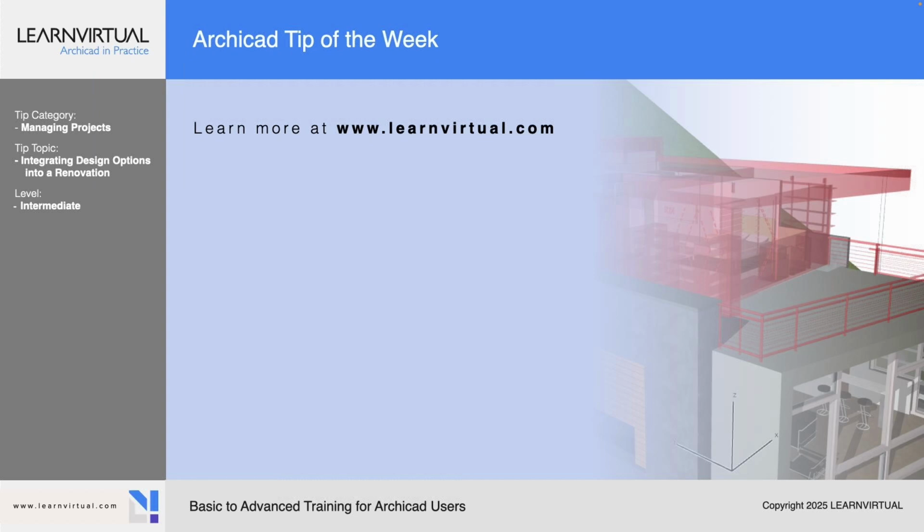The other way you can do it is by relinking it using your design options palette. So for example, if I select this shading device above the door, I could then select the option I want it assigned to and hit the relink button. Maybe this was assigned to option 1 originally, because it shows that in green. If I click option 2 there, I can relink it to option 2 using this method as well.